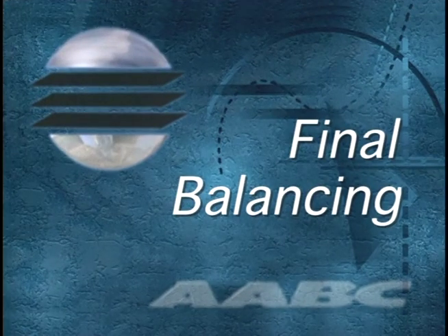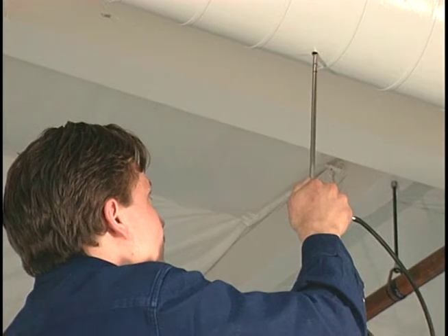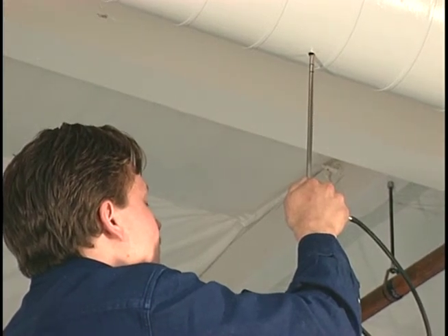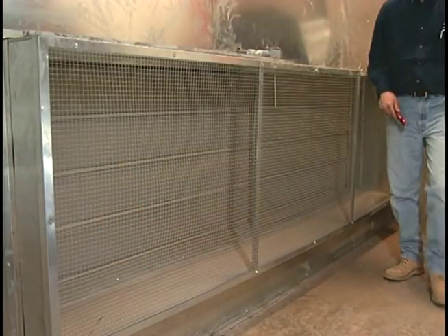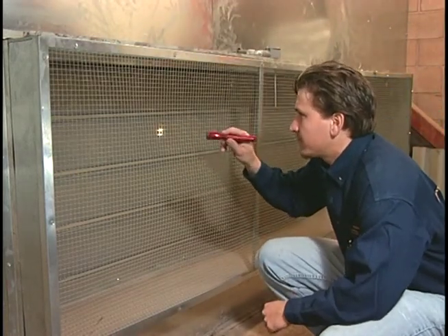Final balancing. After the supply and return air terminals are balanced according to specifications, the technician goes back to the fan unit to set the required minimum outside air and record the final system data.